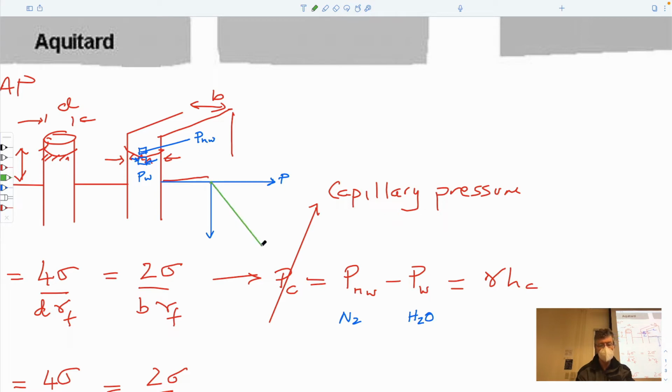Right? We know that, what do we know? We know that the unit weight of fluid is equal to the rate of change of pressure with elevation. Negative sign because we usually have Z going upwards, but we don't in this case. And so if we look at what this would be, then this is dP, this is dZ. So these are the same, right? So this would also be equal to unit weight of fluid and 1. That's the other way, how we always thought about that before.